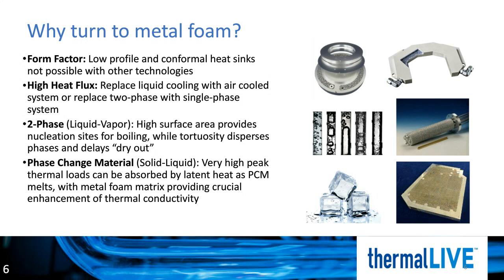Another area for consideration with two-phase flow is when pool boiling or flow boiling are indeed required. Using metal foams, high surface area and ability to disperse the phases and prevent departure from nucleate boiling or dry out result in higher heat transfer coefficients and critical heat fluxes for a more efficient cooling system.